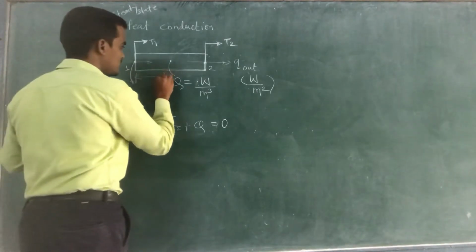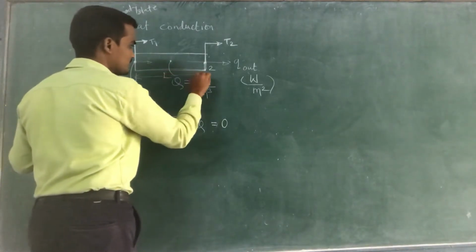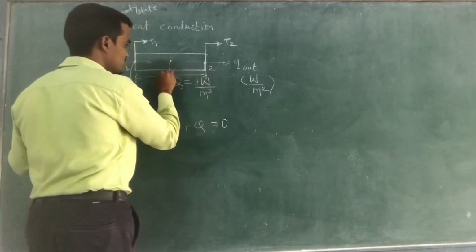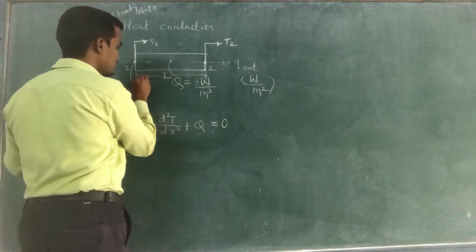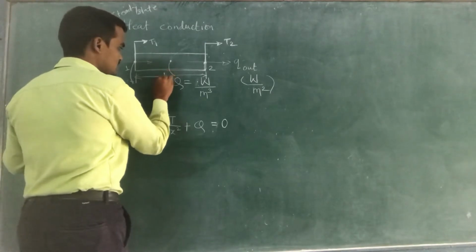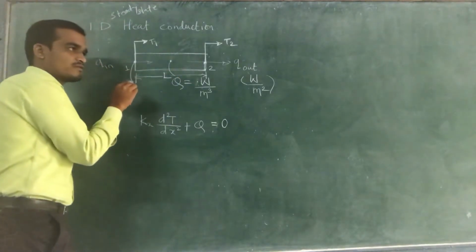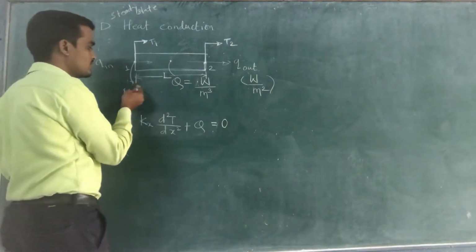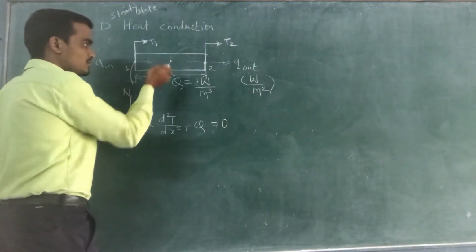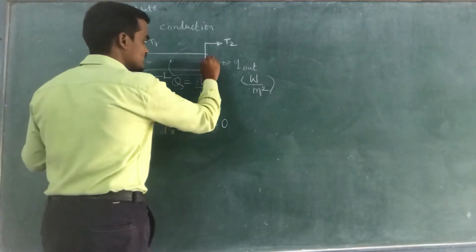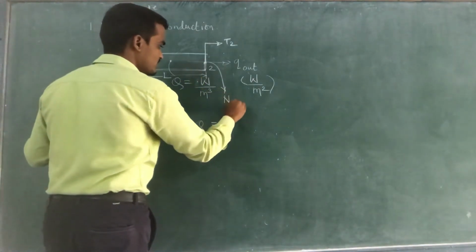Suppose the length of that element is L. If we consider the length of that element is L, as we have derived in our first unit for the one dimensional bar system or the one dimensional spring system. In a similar way we can derive for this system also, and for the second node the shape function will be N2.